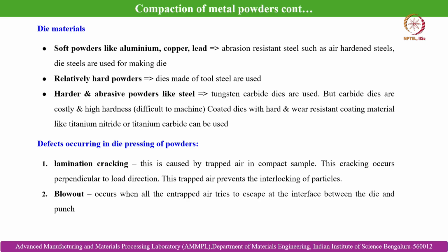One needs to be careful. Sudden impact or a drop can cause breakage of the functional parts or the intricate geometry. So, hence it is advisable to use die steel, tool steels, which along with the required level of strength and abrasion resistance also offer some level of ductility, which increases the longevity of the dies to a greater extent.